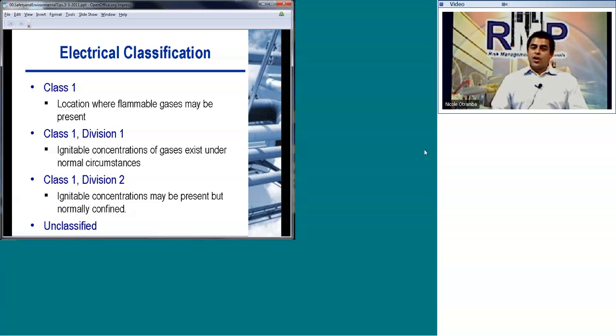Now, usually the question is, well, the vent is actually a safeguard from overpressuring the vessel. And the way it works is if it's actually going to initiate that safeguard fairly often, then you have to count that as the normal. Even though it's not the recommended operating, it's the actual normal operating. So typically vents, and another one is maintenance. When you're doing maintenance on certain vessels or tanks, depending on how the maintenance is done, it could be a Class 1 Div 1 area while that maintenance is going on.